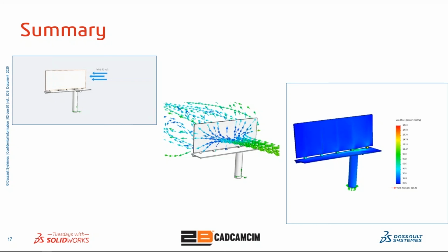The flow simulation gives us the opportunity to export results, pressure or temperature, even convection loading, to a SolidWorks simulation for a linear static analysis. From here, we can further evaluate the response of our structure.